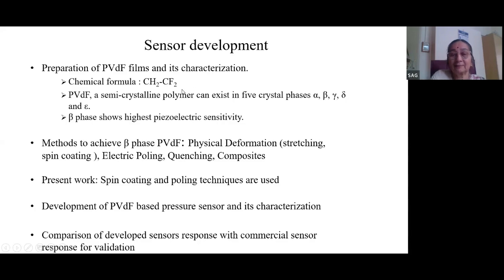You may ask whether this polymer is available commercially. It is available, but you have to get it tailored because PVdF films are used for different purposes. For this particular pulse, you need a beta phase, and this becomes very expensive, at least for people in research.